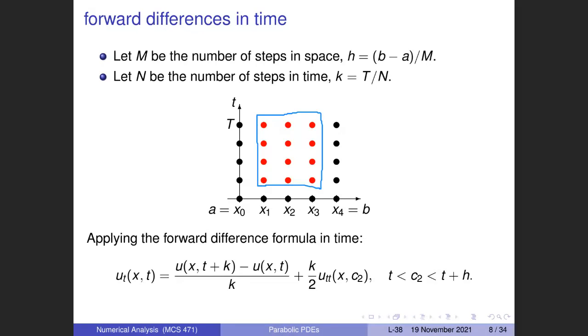It's important to remember that we have an initial temperature distribution. So at time equals 0, we have the function f that will define the temperature, and then we have a left bound and a right bound. So we have the 3 functions. So r is a function of time, L is also a function of time. So the black dots are the points where we know what the temperature will be. The red dots are what we will compute.